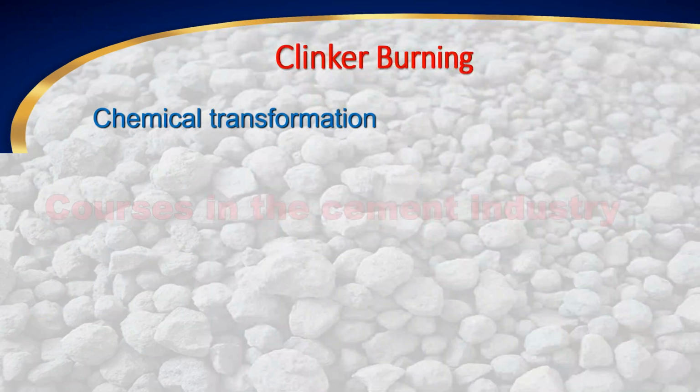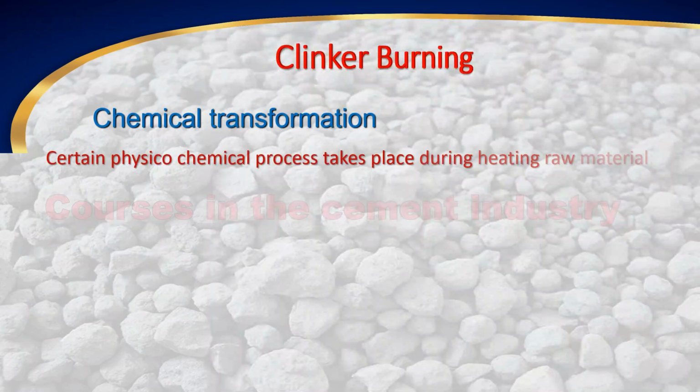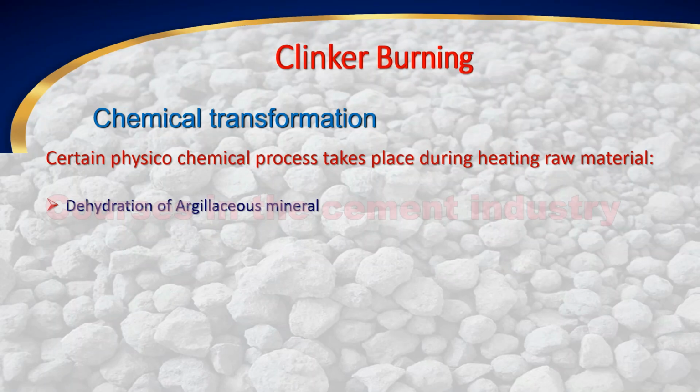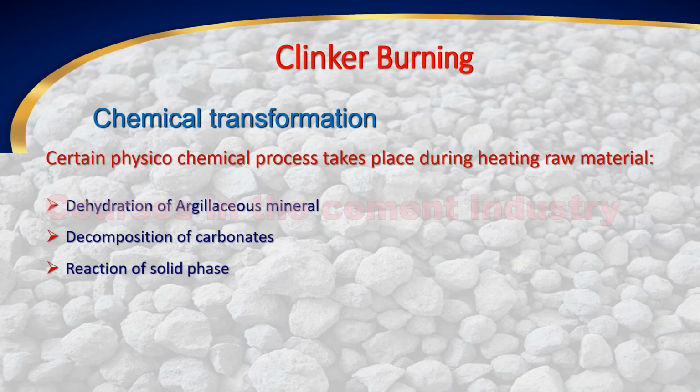Chemical transformation. Certain physico-chemical processes take place during heating of raw material. 1. Dehydration of argillaceous mineral. 2. Decomposition of carbonates. 3. Reaction of solid phase. 4. Reaction of solid phase in presence of liquid phase.